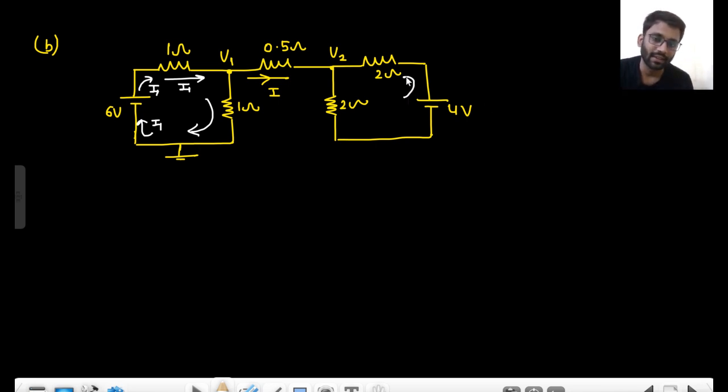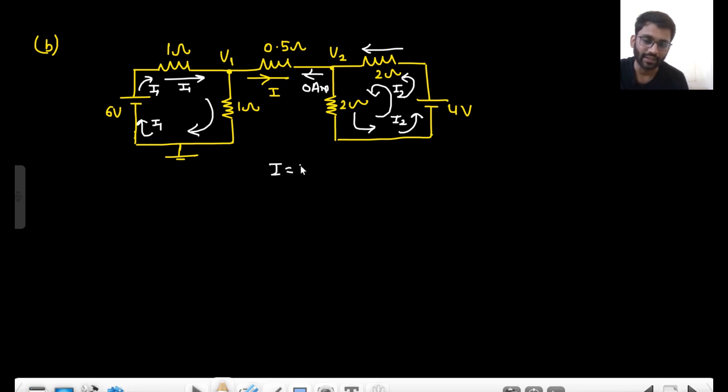You can say that if this is giving I2 current, that means I2 current is flowing like this. It will take back the same amount of current. Now this I2 current doesn't have any path, so it has to flow like this. So in the complete loop, I2 current is flowing. That means there is no current going this way, right? So again here the value of I is 0 ampere. And since this I1 current is going like this and there is no current going here, that means this I1 current is flowing here. Are you getting this point?